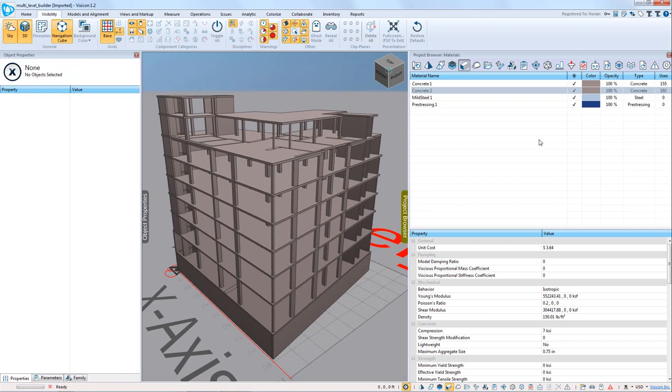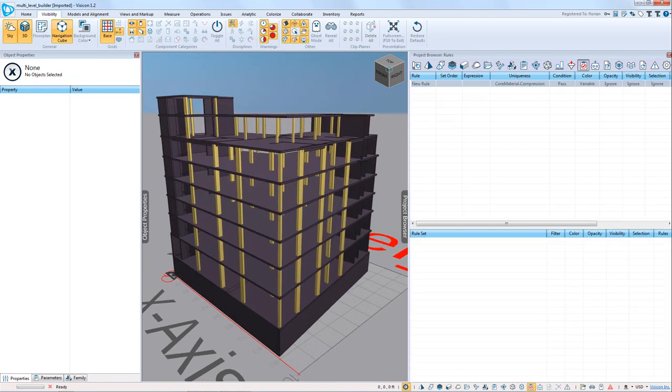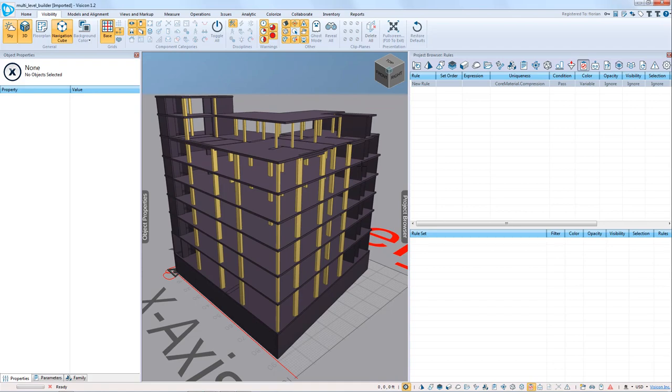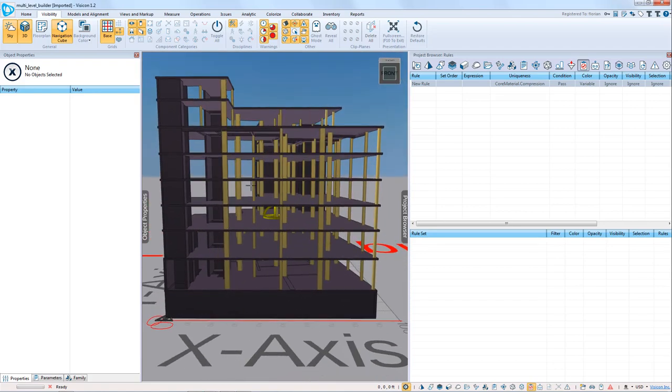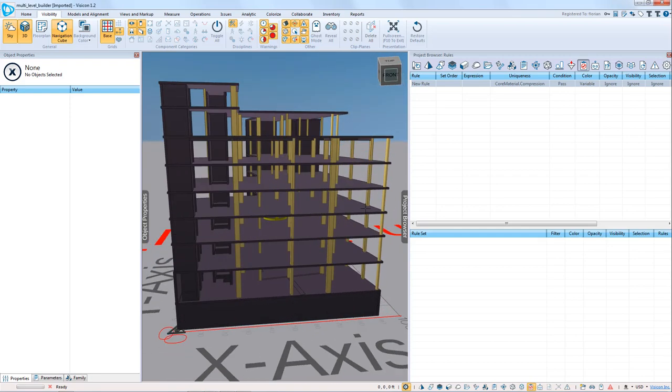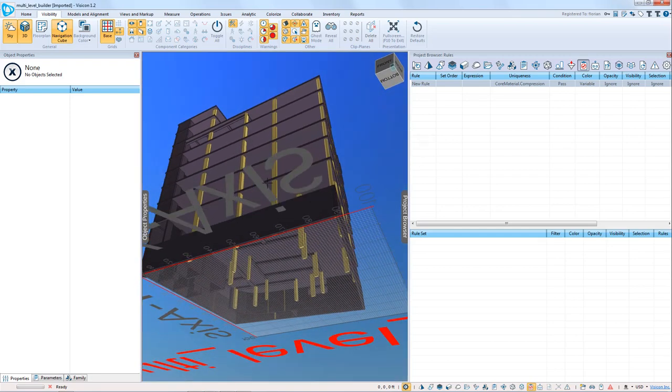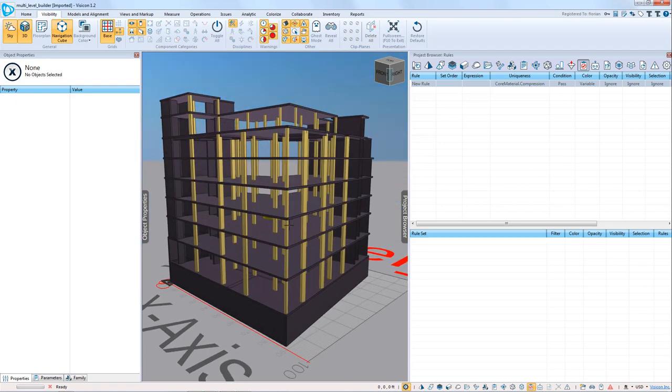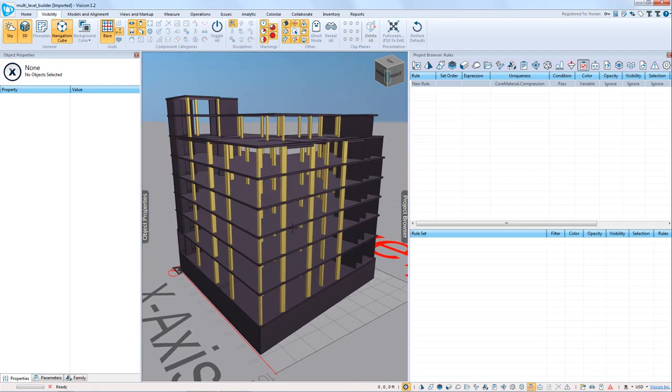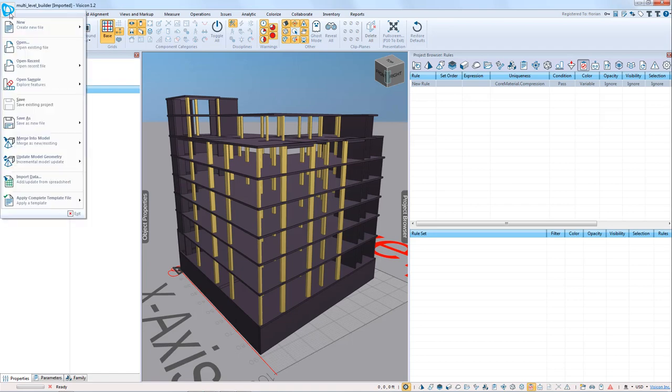So you could check each one individually, but really the benefit of a rule is I can take any model, doesn't matter how big or complex it is, I can apply this rule and immediately do a quality control and interrogation and be very clear about how many different material strength assignments I have applied. So this is how a rule is set up. But you can also make this more efficient by storing predefined rules. So we're going to apply those. We're going to go to File, Apply a Template. So we're going to apply a set of rules that I saved called Adapt Model QA.